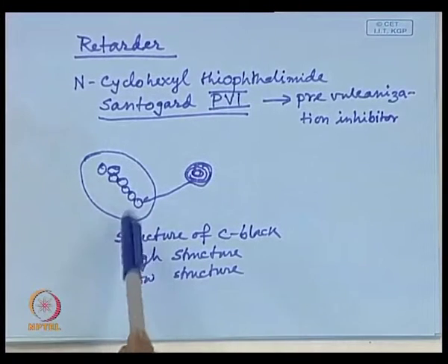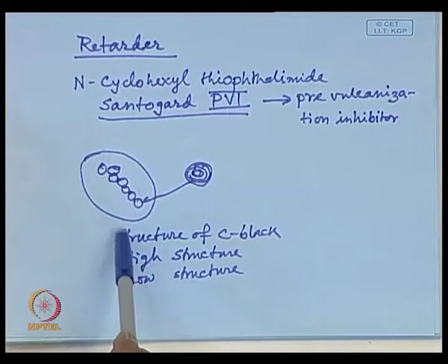In order to overcome those problems, what do we need? We have to properly disperse the carbon particles within the rubber. So, here the problem comes: high structure carbon black particles are difficult to incorporate, but easy to disperse, because they are not prone to form aggregates, because of their bigger particle size and bigger nodular structure. So, they are difficult to incorporate, but easy to disperse.